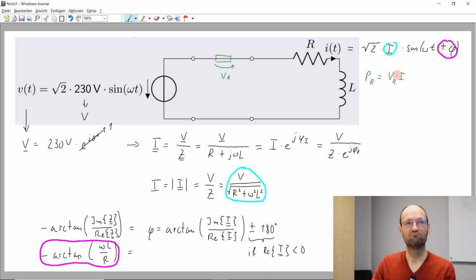How could we calculate the voltage from the current? Just using Ohm's law: current times resistance. If we insert that there, we end up with R times current squared. So to lower these transmission losses, we have two ways.